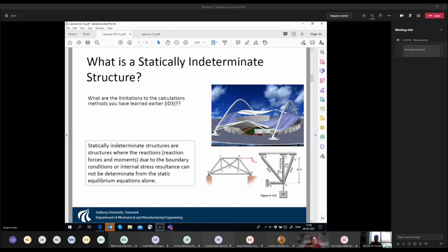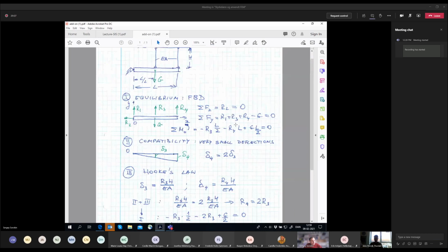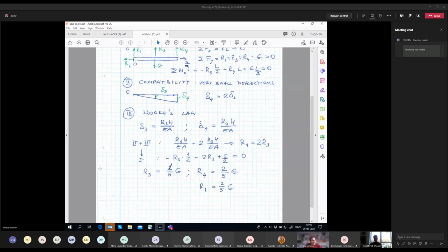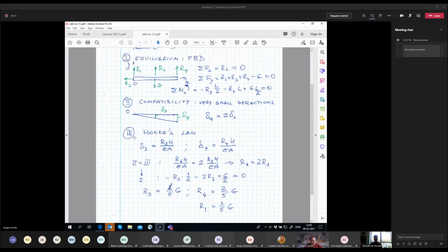So then it gives you all the requested amount of equations, but again it blows up, because you remember that for equilibrium we have only 6 equations. In a plane structure we have only 3 equations, but the number of interconnected elements may be thousands. So the vast majority of these equations are equations of compatibility. Then we do the statically undetermined structures. So if you can survive with these concepts, and remember you are supposed to explain it convincingly in the exam in 3 weeks time.